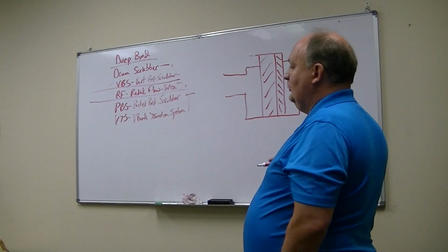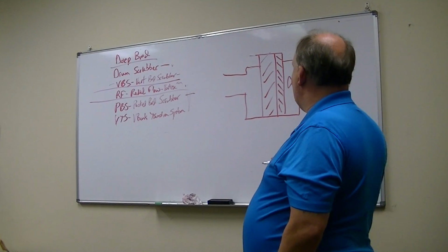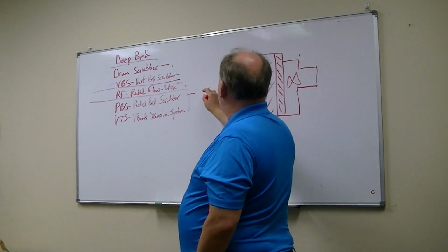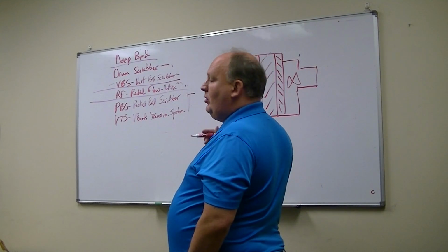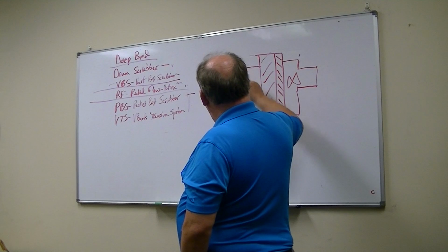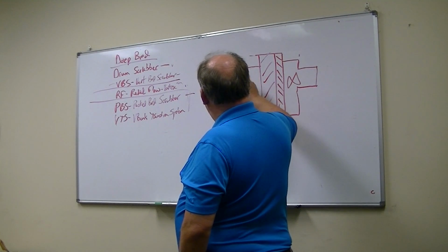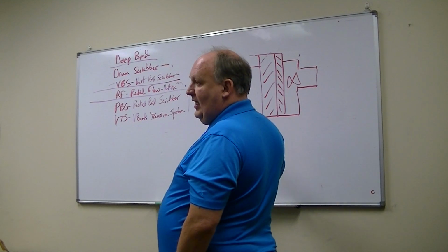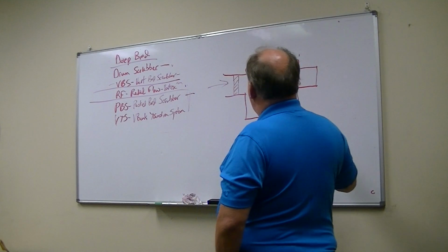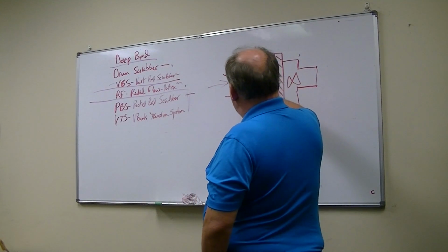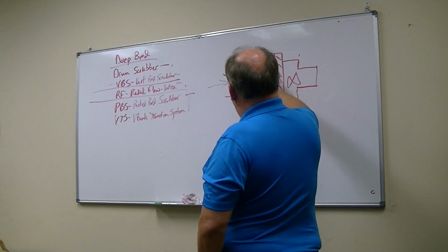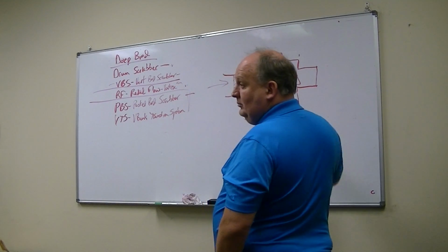All right, so the basics are that a PBS has a horizontal flow design. If we're using it in an odor control application, we're typically going to put a mist and grease filter at the inlet, and then we'll have some plenum space that allows the air to spread out.